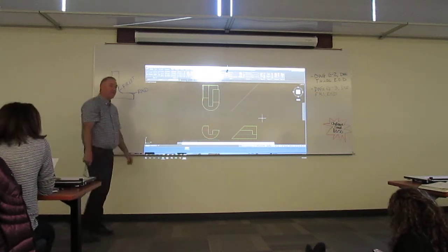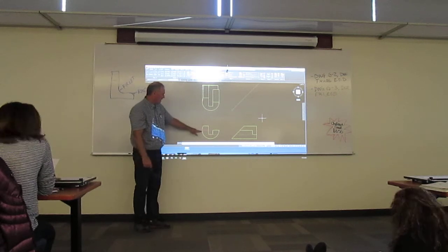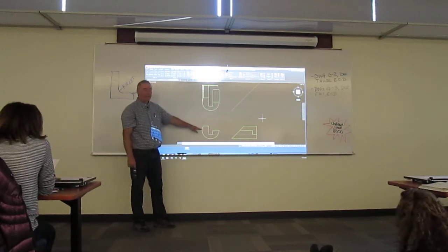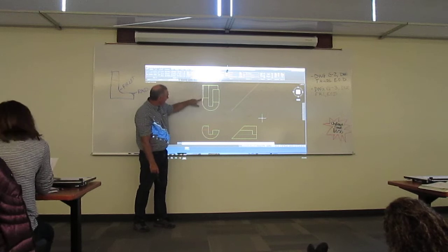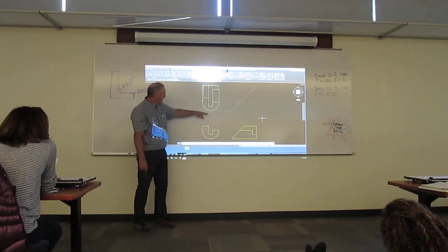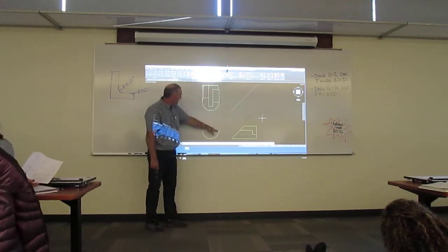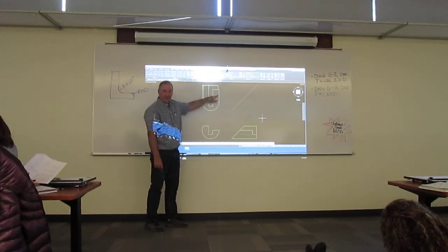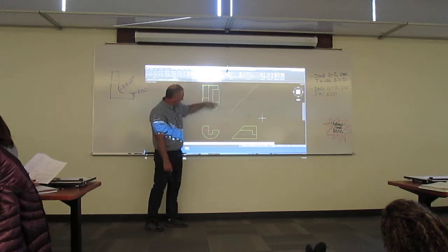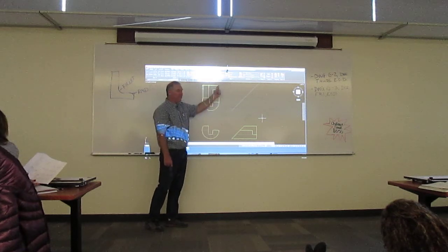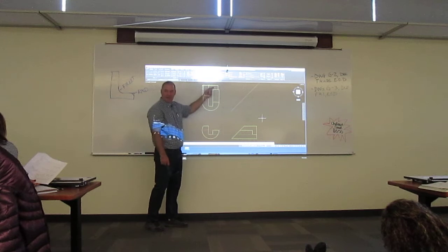Again, the thing you really want to pay attention to as you do this, where are you at in relationship to this center line, that limiting element? In this case, I had to keep wrapping around. This one was before, so it's internal, so it really didn't matter. This one's right on it, so that's the limiting element and the edge of the plane. This one occurs before it, so I'm removing that limiting element and coming into the plane.